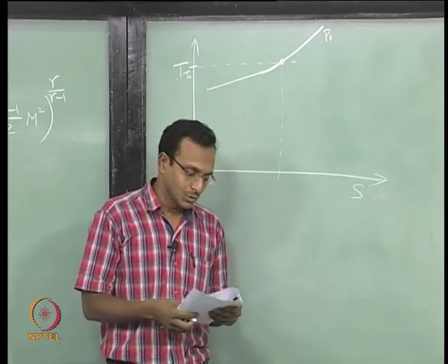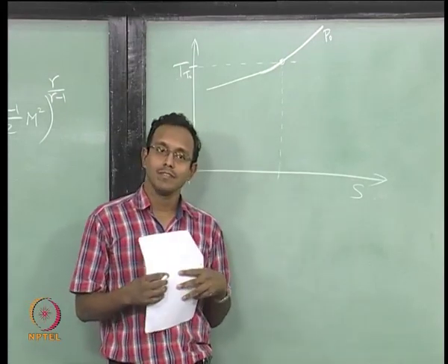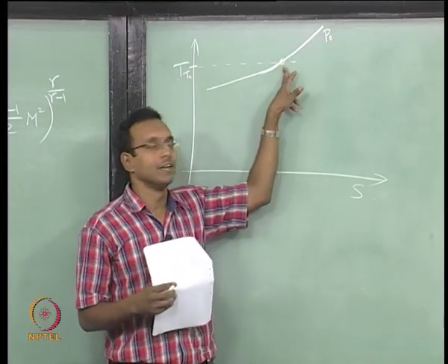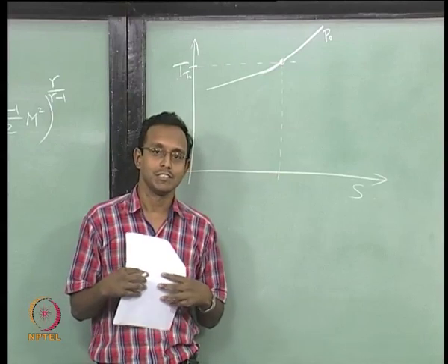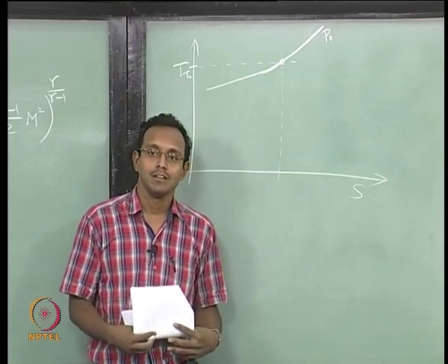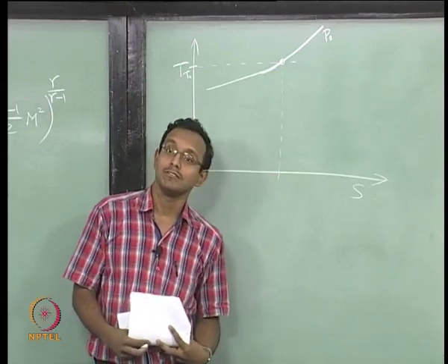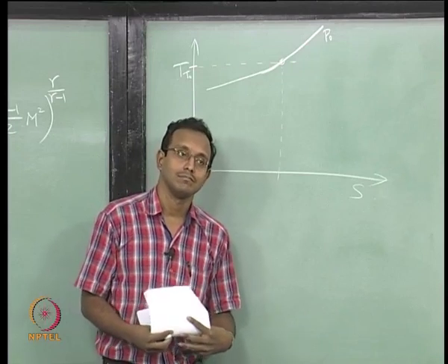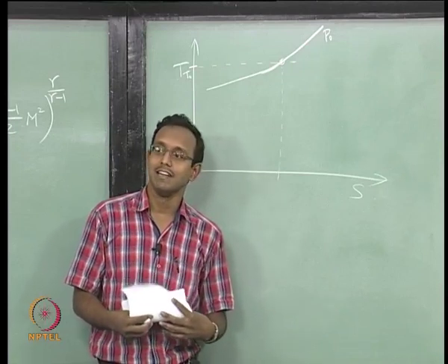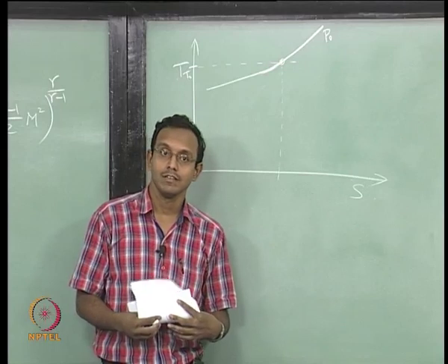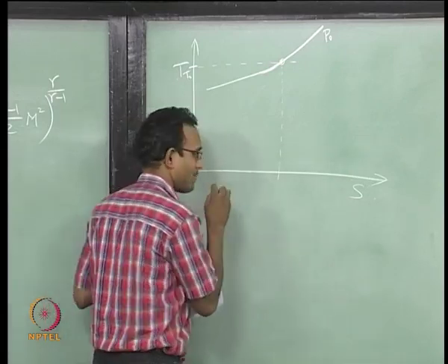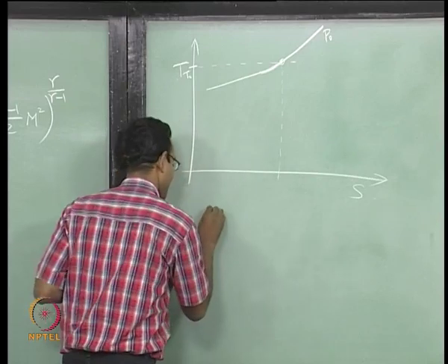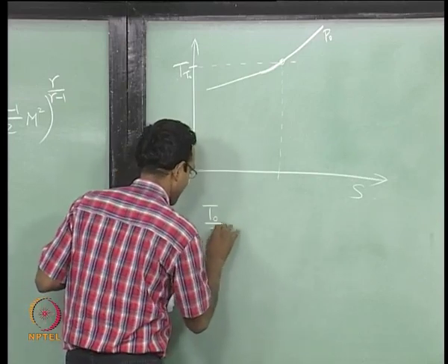Okay. So let us say I am going to accelerate this fluid to some subsonic condition, some subsonic velocity. What will happen to my pressure? It will decrease. Why? What happens to temperature? Easier to look at is temperature.